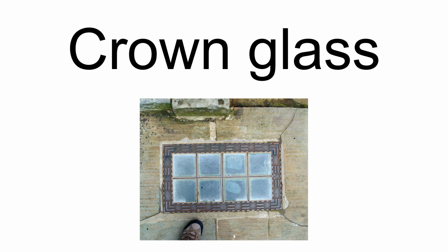One of the earliest methods of glass window manufacture was the crown glass method. Hot-blown glass was cut open opposite the pipe, then rapidly spun on a table before it could cool. Centrifugal force shaped the hot globe of glass into a round, flat sheet. The sheet would then be broken off the pipe and trimmed to form a rectangular window to fit into a frame. At the center of a piece of crown glass, a thick remnant of the original blown bottleneck would remain, hence the name bullseye. Optical distortions produced by the bullseye could be reduced by grinding the glass.